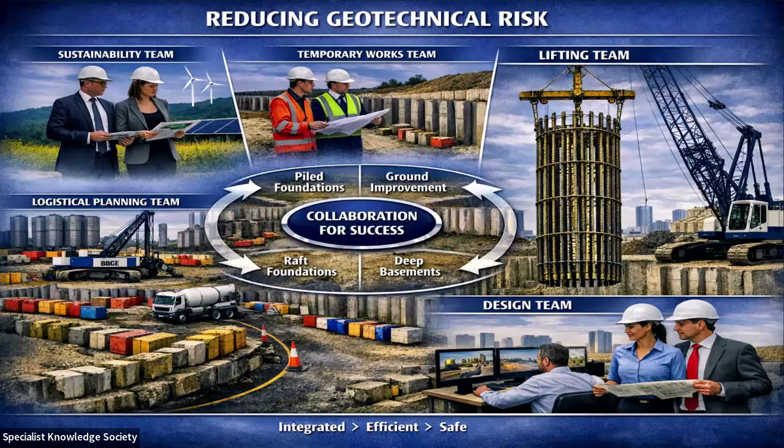Again, the remediation of that is only breaking out and recasting in remedial areas of that wall. But the solution really is to ensure, one, you've got a good concrete mix that flows properly, and two, you've got a diaphragm wall cage designed with adequate spacing in it to allow concrete to flow. From my perspective, they would be the two main areas of defects. There could obviously be a lot of others, but I'll stick with those two at the moment.